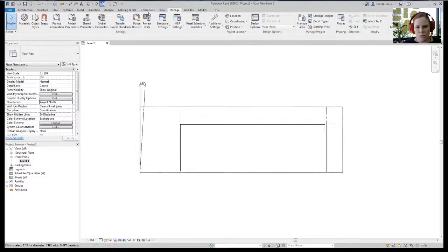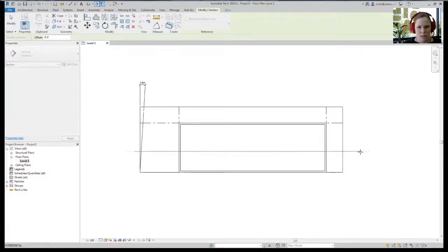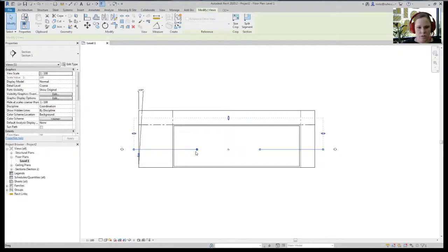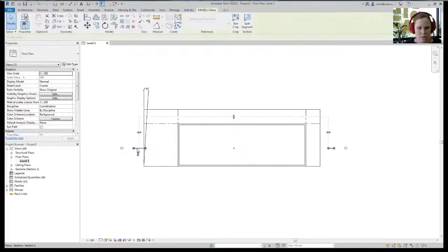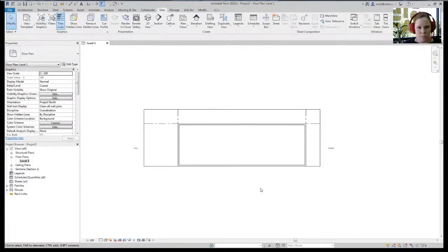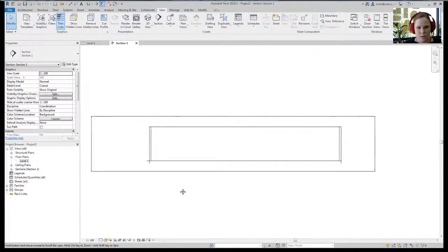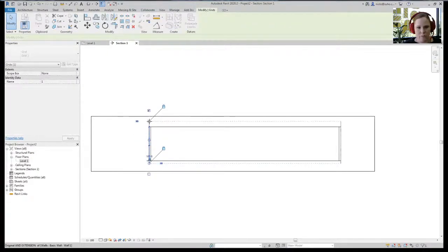So when we're drawing in Revit, I actually draw on Project North just to make sure that my lines are all straight. So I've done that in this instance. And just to show you, I've just drawn a section through. And again, I'm going through this quite fast because it is a lengthy video, but you'll be able to revisit this and replay it and watch it. So this section line, if I go to that view, it basically is cutting through the building and it's showing some walls that I have made.